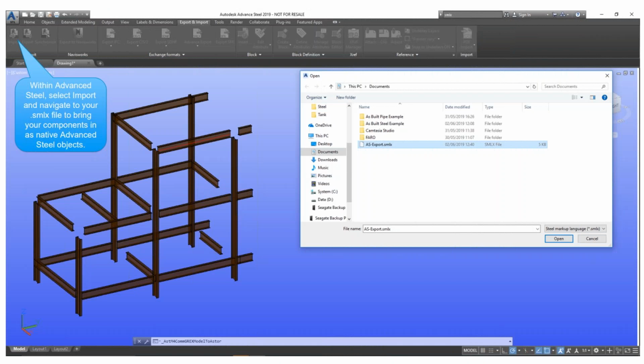And the beauty is these SMLX file formats can also be used if it's something related to steel structures which you want to import in Revit. Revit also has this functionality of importing SMLX files. Plant 3D also has the capability of exporting to Revit, Advanced Steel, and any other tools which are available. So it converts these objects into intelligent objects. So that's the whole process of using the as-built scan tool coming in from Faro, and these as-built scan tools could be utilized for converting those details into intelligent information.